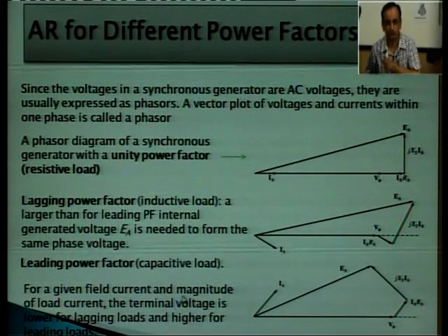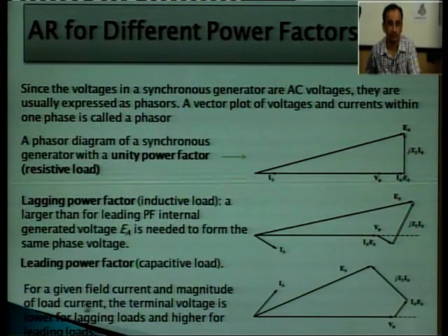It is very interesting to see that for a given magnitude of load current, the terminal voltage is lowest for the lagging power factor and higher for leading loads. So, we can see that